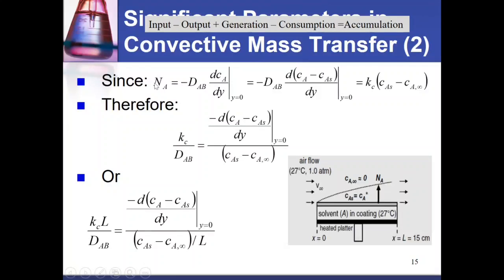If you multiply this flux by area, you get the molar flow rate. If you multiply by area and molecular weight, you get the mass flow rate. In this balance, since we have no reaction, mass is also conserved. So moles in should equal moles out.